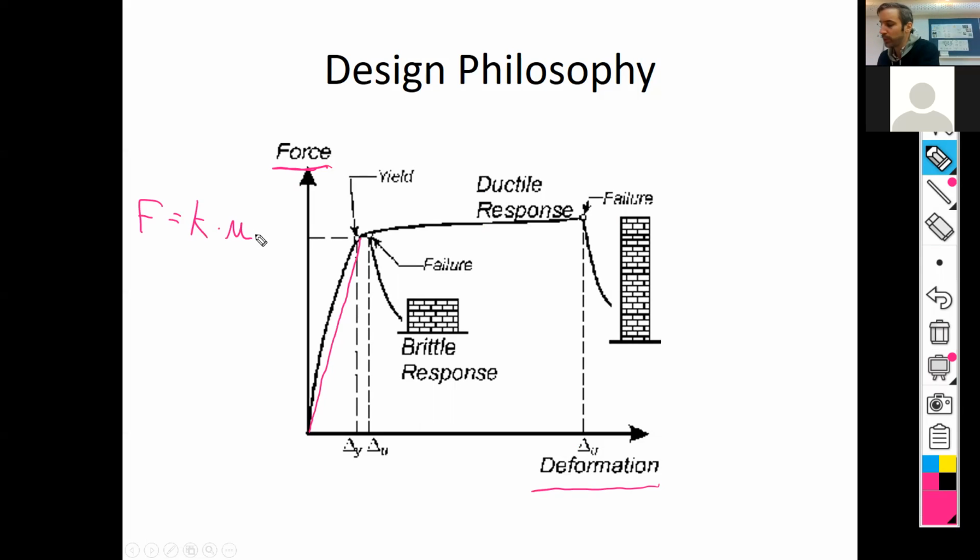But at this point, we reach yielding and we have an almost flat response, okay? And a brittle structure will fail almost immediately after yielding. A very ductile structure will fail with a much larger deformation.